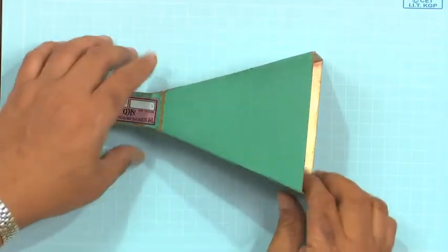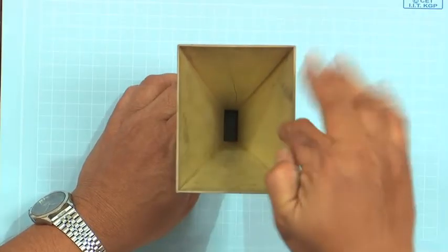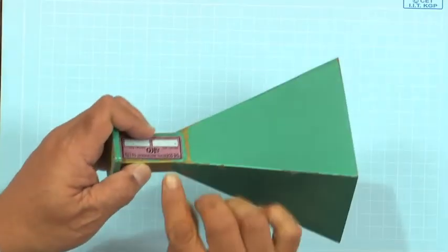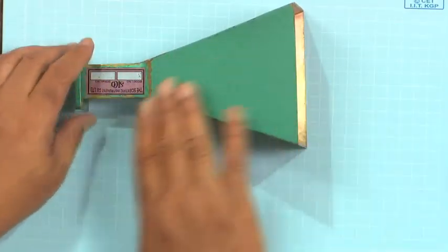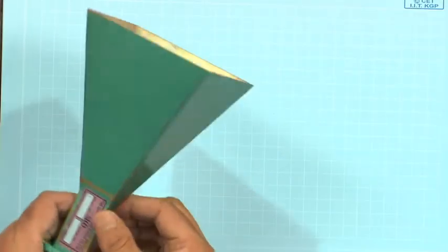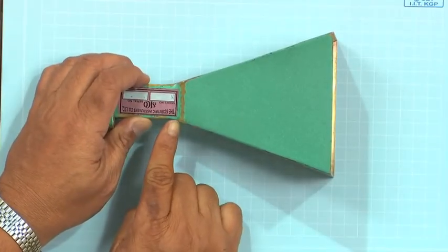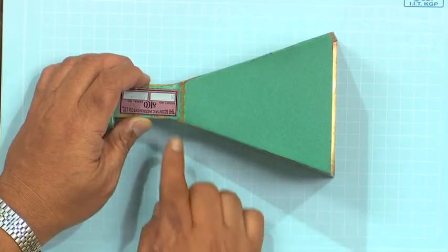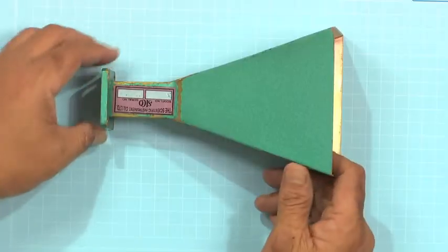Then people thought that obviously a better thing will be if both E and H plane are flared like this. I think all of you have seen this many times, this is called a pyramidal horn. In both directions you see that this plane also is flared, this plane also is flared. This flaring is the H plane flaring, this flaring is the E plane flaring, both are flared. But remember the very important point, that when it was constructed, from the same point when the E plane flaring started, the H plane flaring also started. This is one of the things that we will have to keep in mind while designing.